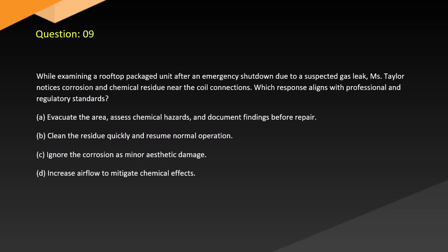Question 9. While examining a rooftop packaged unit after an emergency shutdown due to a suspected gas leak, Taylor notices corrosion and chemical residue near the core connections. Which response aligns with professional and regulatory standards? A. Evacuate the area, assess chemical hazards, and document findings before repair. B. Clean the residue quickly and resume normal operation. C. Ignore the corrosion as minor aesthetic damage. D. Increase airflow to mitigate chemical effects.